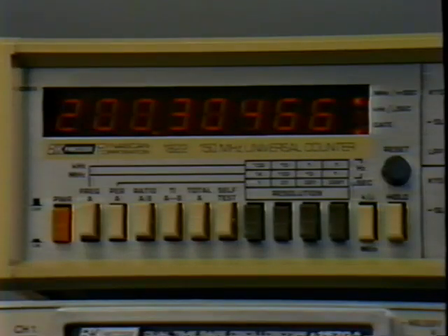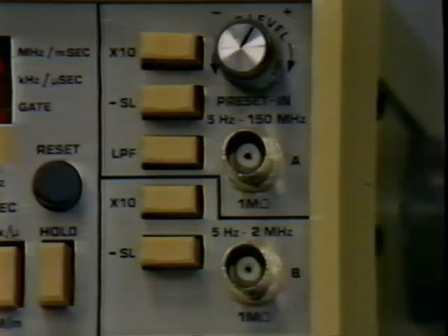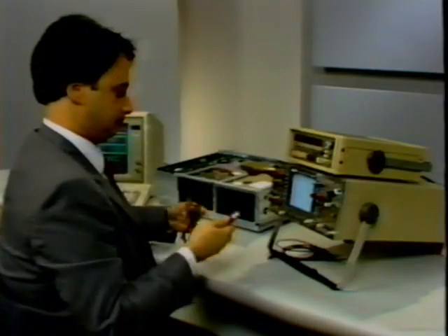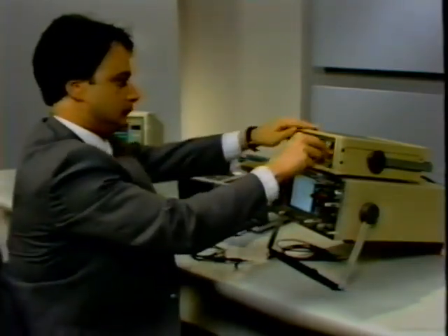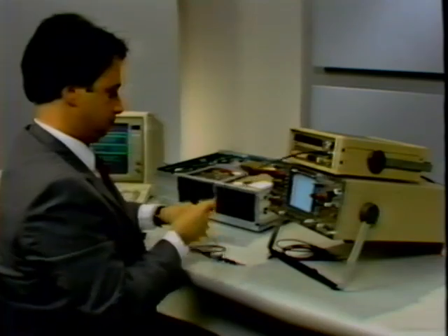These units measure and calculate duration internally and present the results on a digital display. This eliminates errors of interpretation that are always present in oscilloscope readings. Like an oscilloscope, this frequency counter has two input channels labeled A and B. However, there is no external trigger jack since the input signal always provides the trigger pulse on these units. The probes used on this counter are interchangeable with those used on 1 megaohm input oscilloscopes.